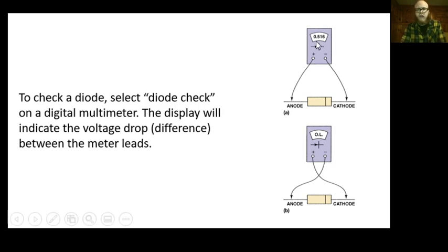Here, we're seeing a very low number, 0.516. This number here is the actual voltage at which it is needed to start that current flow. So if I put 0.4 volts to this, no current will flow through it, or if any does, because if you get into some of the nitty-gritty stuff, like micro, so millionths of an amp will flow through these when they're not biased, but like, what's that going to do?